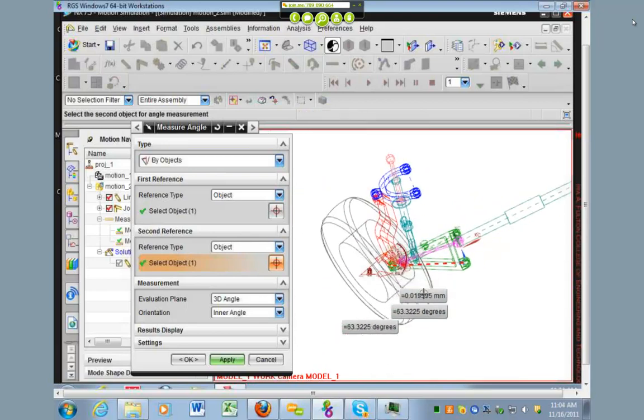And there it showed us exactly what it is currently. So you can perform angle and distance measurements with this method within any articulation or animation task at any point in the paused simulation. If you want to stop your simulation, your articulation, at some point and see what the angle is at that moment, that's how you do it. So that is the tutorial. It's pretty simple. Once you've done this, you can just do what Larissa showed.